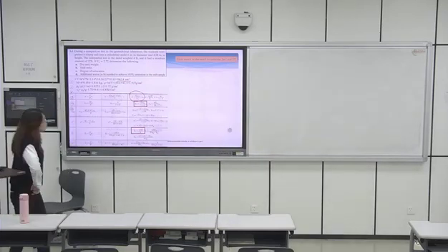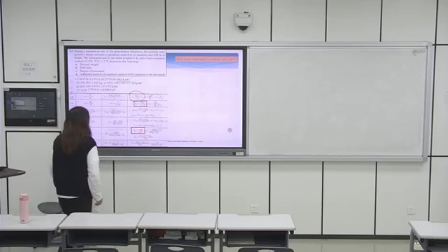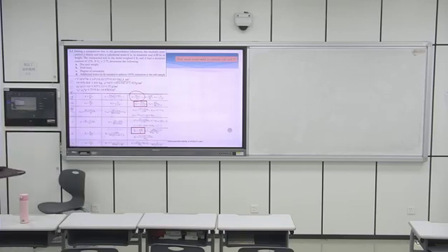So you need to calculate how much water is needed to saturate 1 cubic meter of soil, right? Let's see. We know the saturated mass. For one cubic meter of soil, the saturated mass minus the moisture mass is the water you need to saturate it, right? That is how much water you need to add to the moist soil to get it saturated, right?